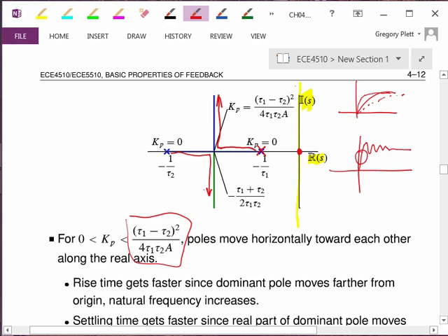And so our job as control engineers, if we use a proportional controller, would be to choose the value of Kp that we think best meets the specifications. And so it may be the value of Kp that puts the poles right there, or maybe we can tolerate a little bit of overshoot to get a faster rise time, and it might put the poles there. Or maybe we really don't want to push that hard. The control effort is a concern, so we put poles right there. But the root locus plot helps us to understand some of those trade-offs a little bit better.